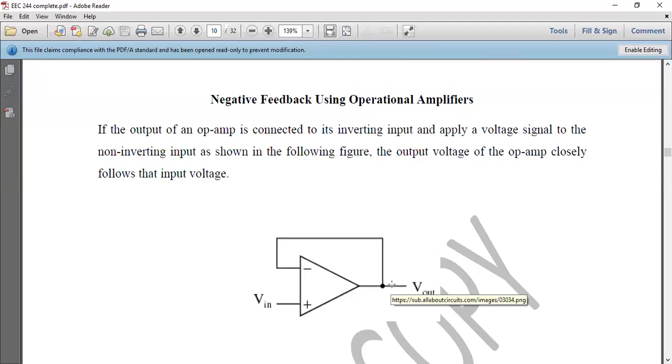On the other hand, if you are sending signal into the amplifier from the positive terminal, that is the non-inverting input, the amplifier will check what is the value of the other terminal and then look at the difference. The difference between the two will be raised up by means of the gain of the amplifier A, but the value will remain positive. If it is positive that came in, it will remain positive outside. If it is negative that came in, it remains negative outside. The amplifier will not invert the sign. And that is why they call this one the non-inverting input. And the other one here that has minus is called the inverting input of the amplifier. I hope you get that.